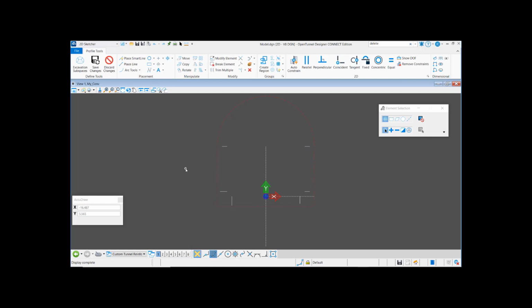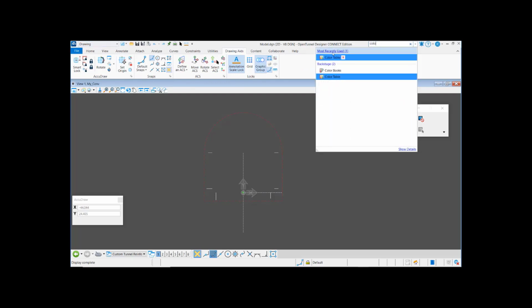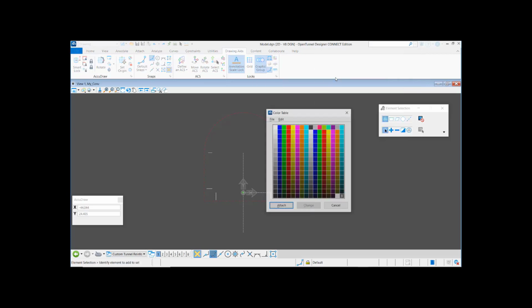Now we will define the excavation subspace, so the different parts in the excavation where we can assign some materials. So for that, I go to subspace definition. That will give me a display of my excavation elements inside my 2D space, temporary 2D space. I will change again the background color so to better see what I'm doing. Let's put it in white.